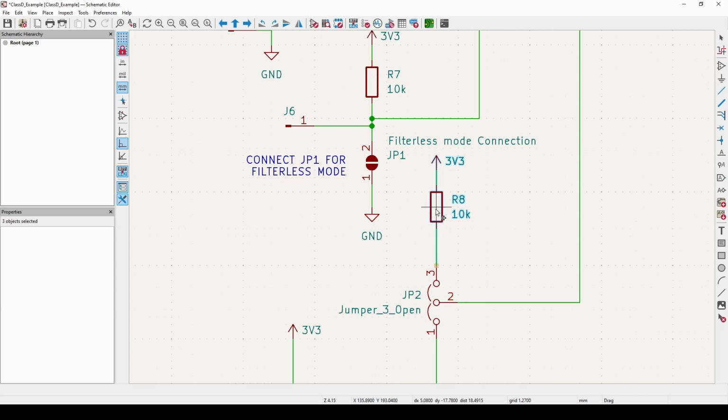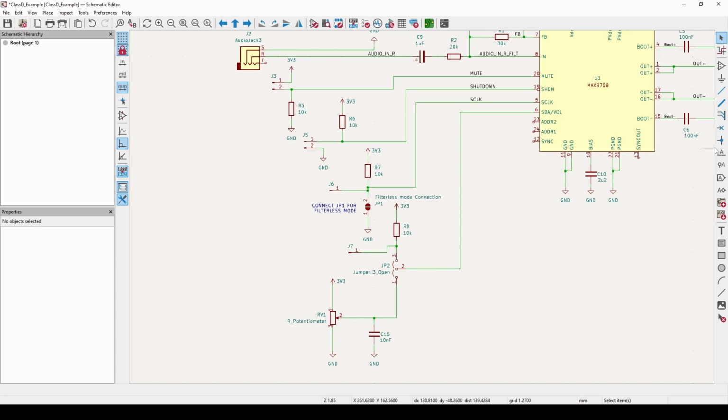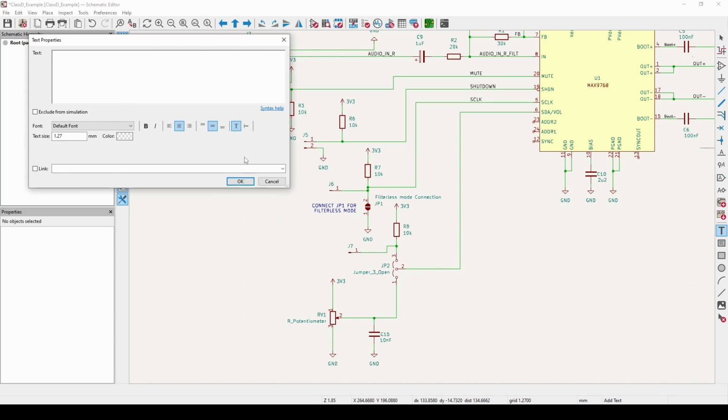Another thing I've missed out from this is the pin connection for the I2C communication. So obviously if I were going to use the I2C channels, then I need to connect to the data line and the clock line, which is on these two pins here. So I need to keep those two connections together on the PCB design. So I'll make a note of that over here.